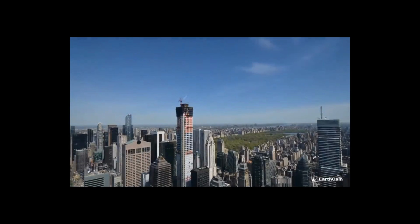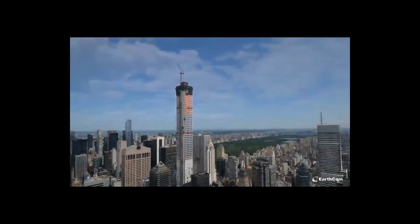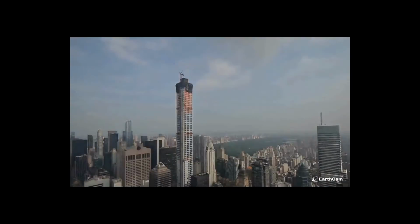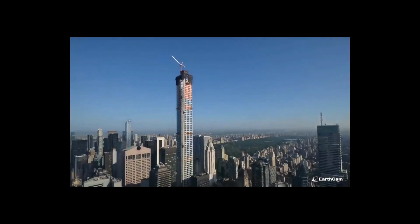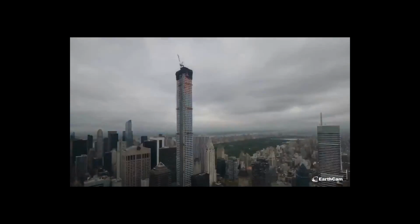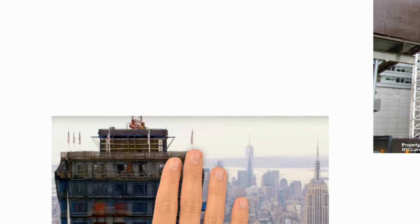The widespread use of in-situ concrete also reduces the amount of different trades on site and avoided the lifting of heavy pieces, enhancing safety. The protective net was wrapped around the slip formwork to prevent objects from falling and providing a safe working environment for the workforce and pedestrians below. Similar netting was placed over the windows as the construction progressed.